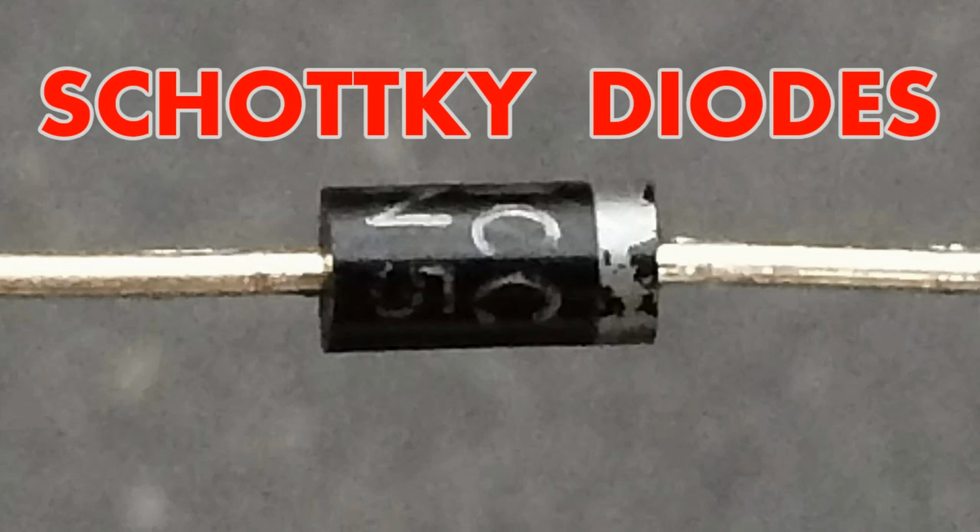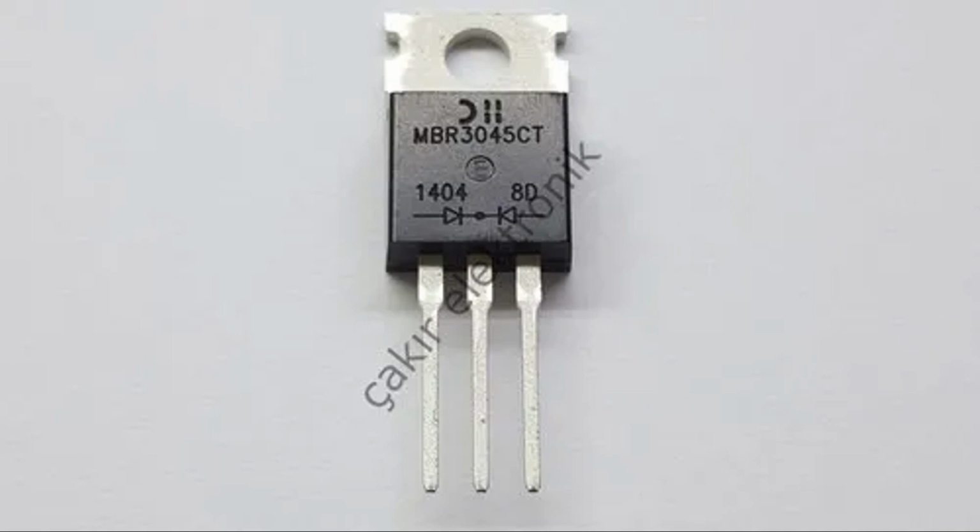However, it's essential to consider that not all diodes have a reverse recovery time. In Schottky diodes, for example, the absence of a p-n junction eliminates the reverse recovery effect entirely, leading to virtually zero reverse recovery time. On the other hand, in standard p-n junction diodes, the reverse recovery time can range from several nanoseconds to several microseconds, depending on the specific diode's design and material characteristics.